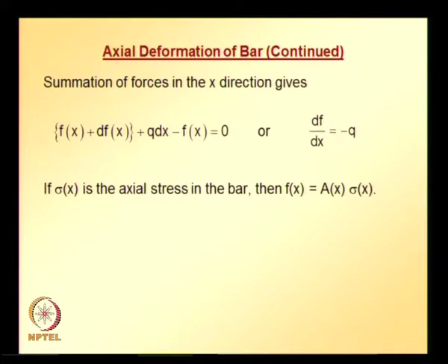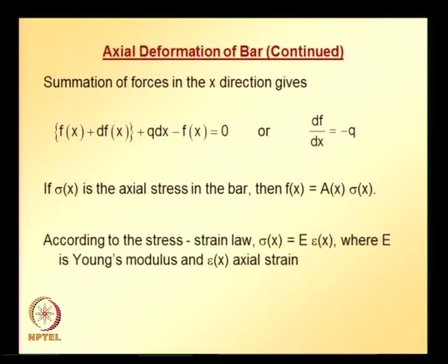And we know that if sigma x is the axial stress in the bar, force Fx is given by area of cross section times sigma from structural mechanics, and also according to stress strain law, sigma is equal to Young's modulus times strain.